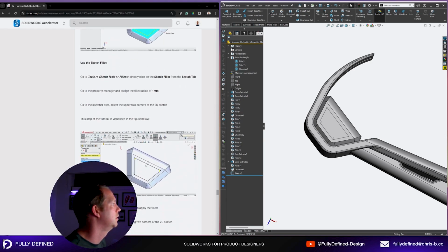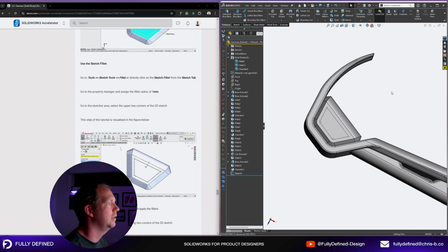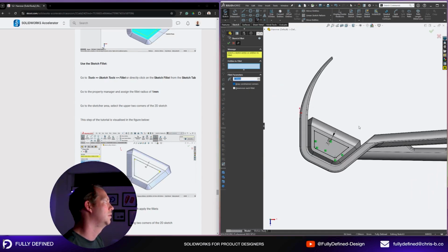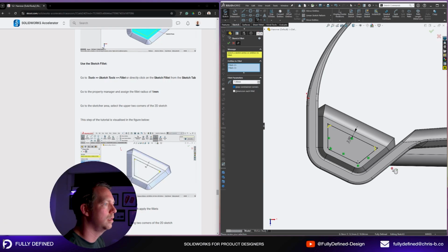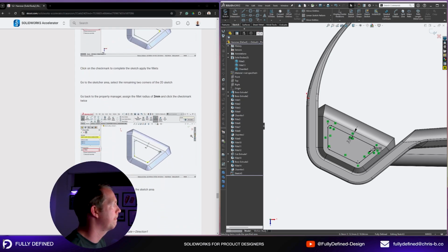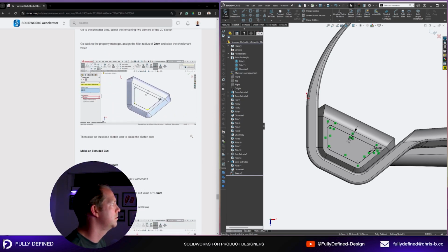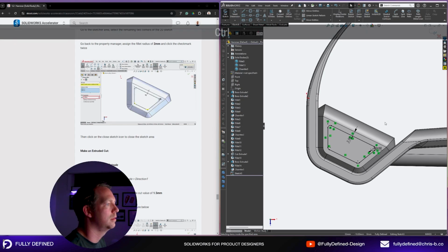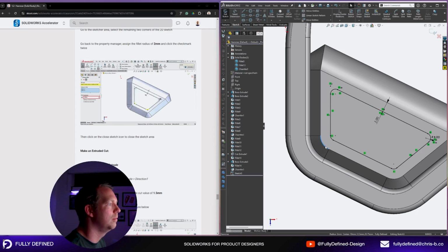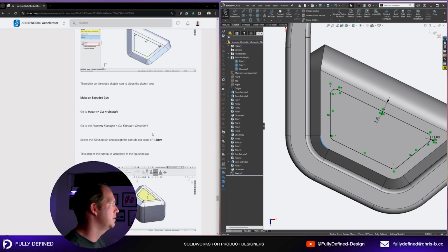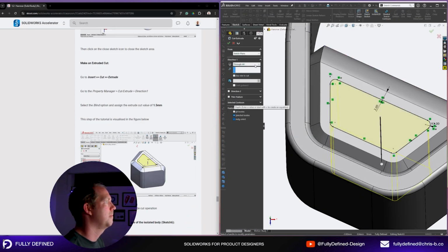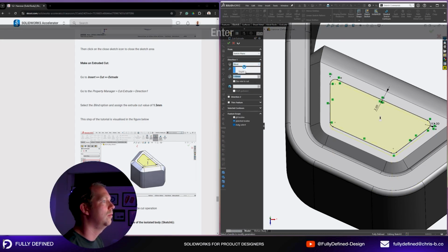Okay, so we're going to add some fillets to that sketch. So I'm going to click Edit Sketch. 1 millimeter radius. And two millimeters on the other ones. But they've already got fillets because they're offset from this edge here. So I'm going to skip that step. I'm going to do an extrude cut, 1.5 millimeter. So change that to end condition blind, 1.5 millimeter down.